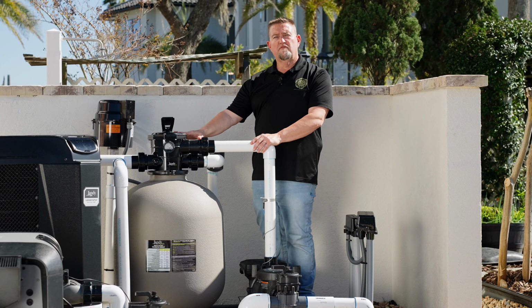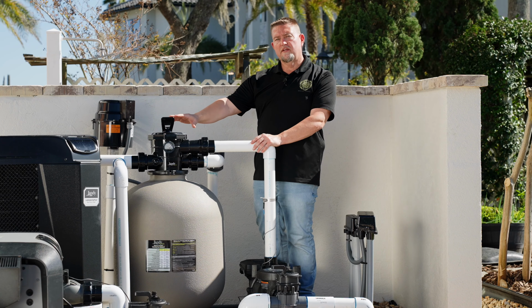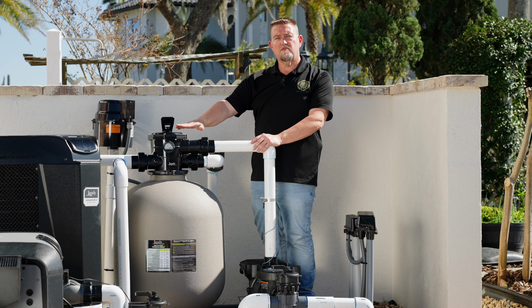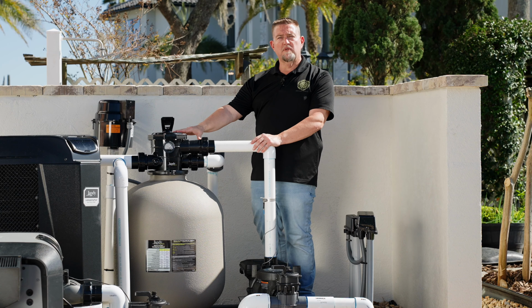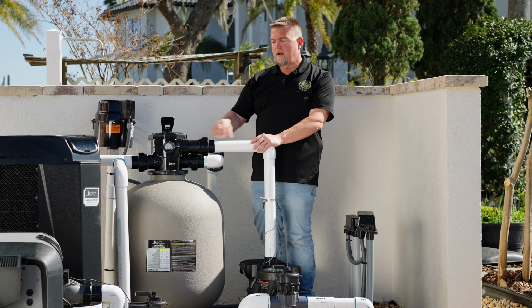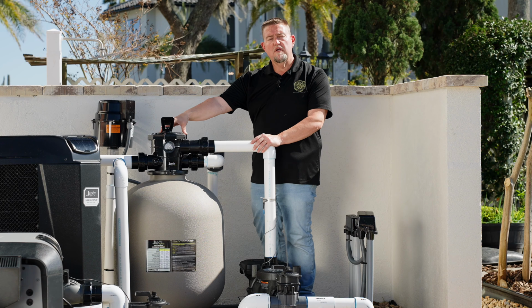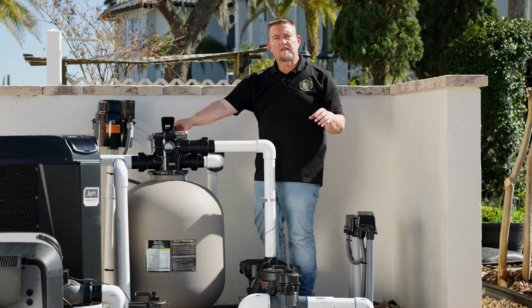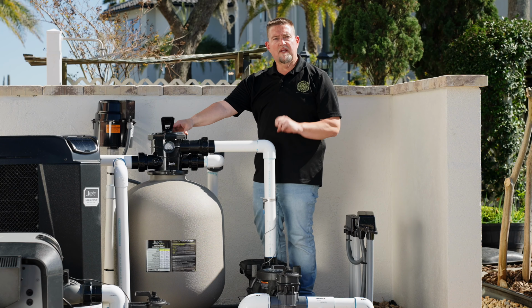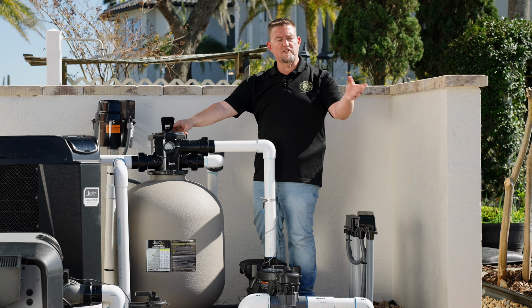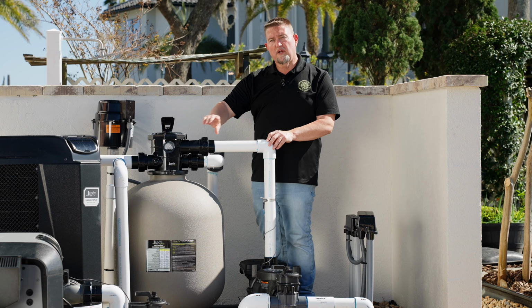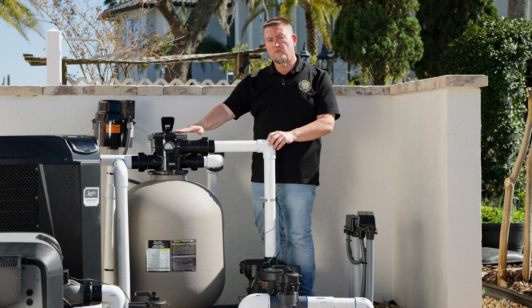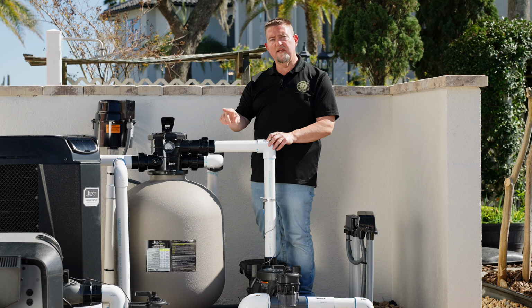Now that we've backwashed our filter, the next thing you want to do is take the valve, rotate it from backwash to rinse. What the rinse mode does is turn the pump back on and actually rinses the inside of this valve. So the last thing you want to do is spend all of your time vacuuming the pool, getting it nice and clean, turning the system on without rinsing, and then whatever debris is left in the valve gets shot back to your pool. So now we're going to take the valve from backwash to rinse, again with the system off, rotating clockwise.